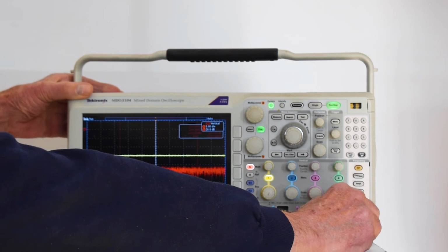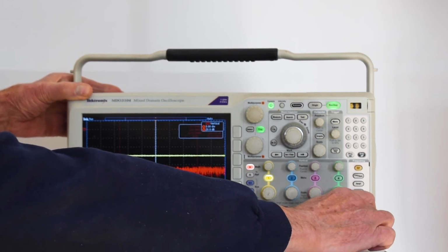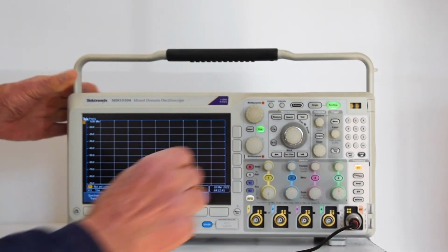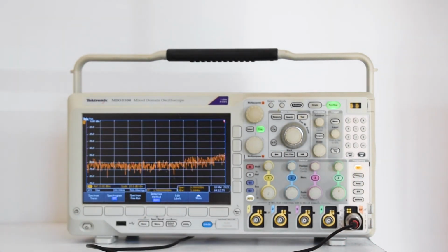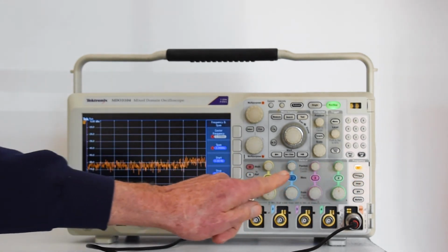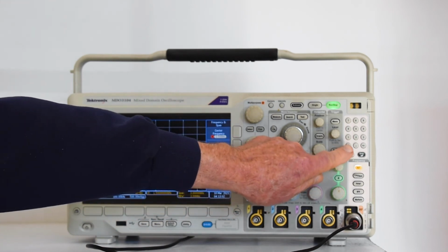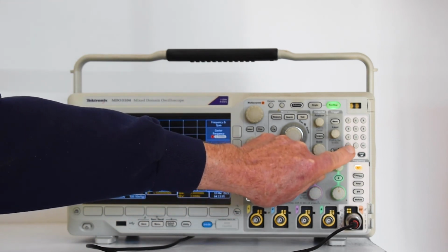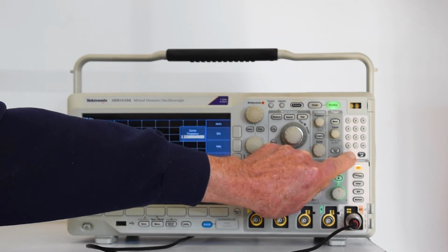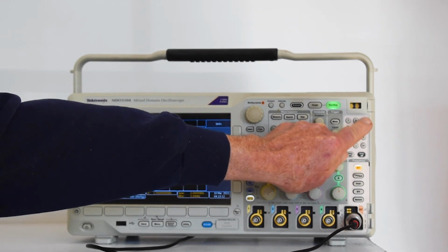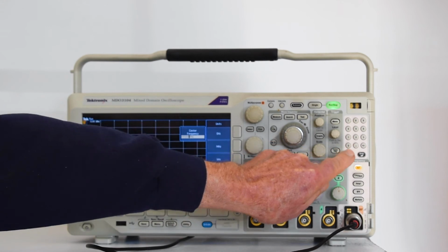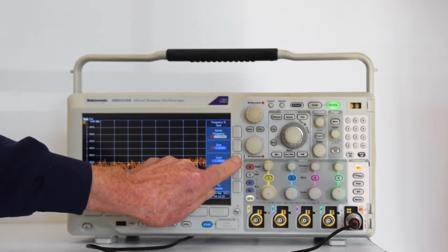To clarify, move the BNC cable over to the RF port. Press frequency span, and for center frequency, enter 100 kilohertz. That puts the fundamental at the center of the screen. Since it is a sine wave, there is not a series of harmonics. By pressing two buttons, the user can have the oscilloscope instantly shift between domains.